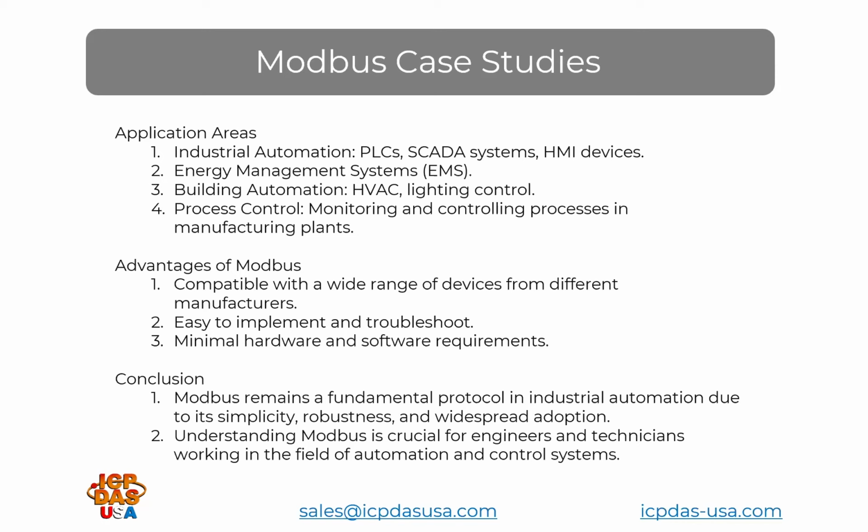But actually, one other situation I ran into is there are companies out there that skip registers, and instead of allowing you to pull, say, six consecutive registers, there's a gap in between. So then you run into communication errors, and you try to troubleshoot, and eventually you find out that they skip it, it's undefined, so therefore you get the Modbus error that way. That's bad practice as well.